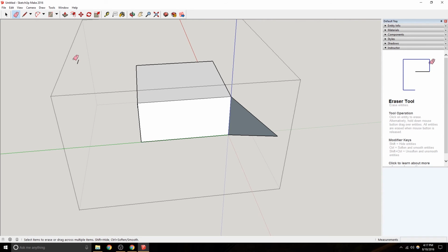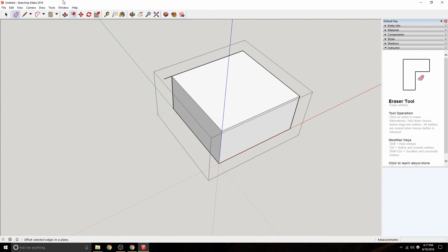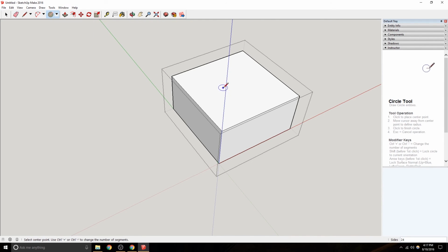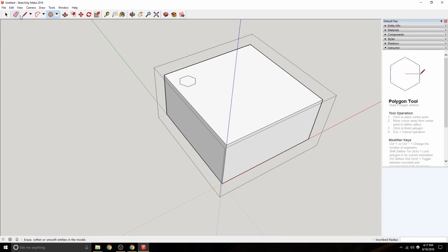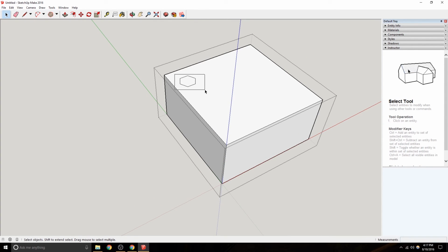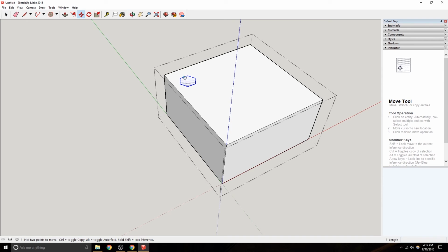What I said before is I was going to show you a through hole. And so a through hole is going to be using a circle. Actually, let's not do a circle, let's do a polygon. So let's say you want to put an M3 nut, or maybe an M5 nut. An M5 nut, the outside of the hex is actually like 8 millimeters. So that would be 8. There you go. And let's say we want to locate it at a certain position that is important.